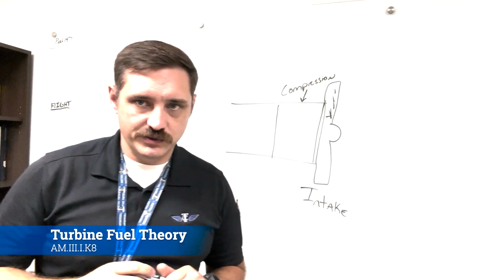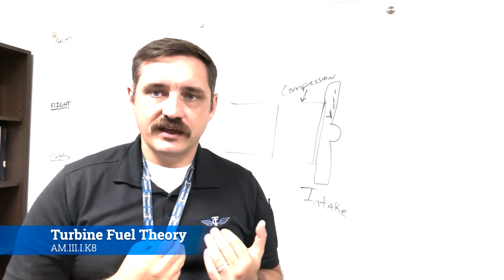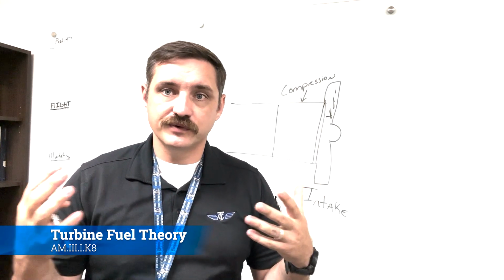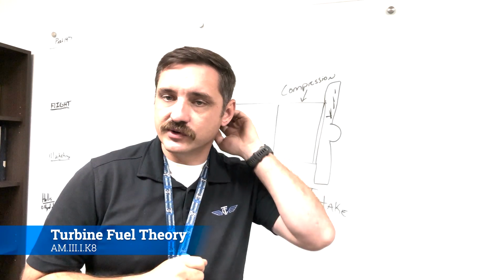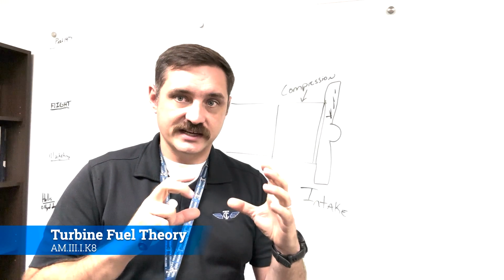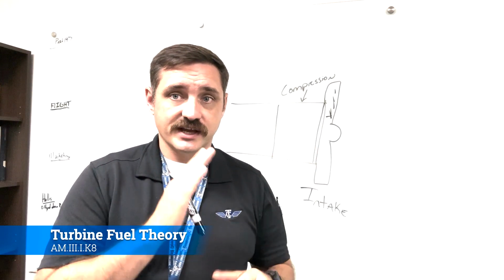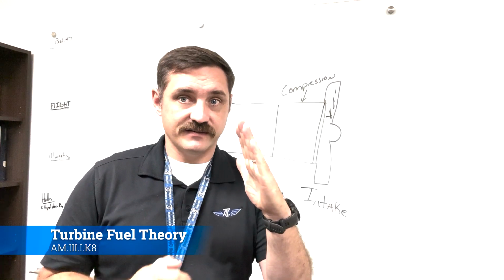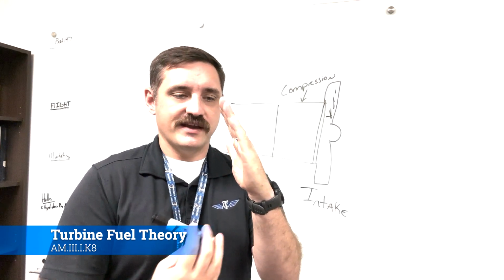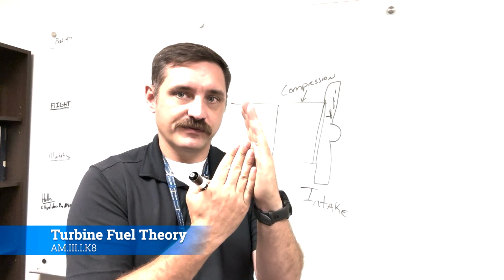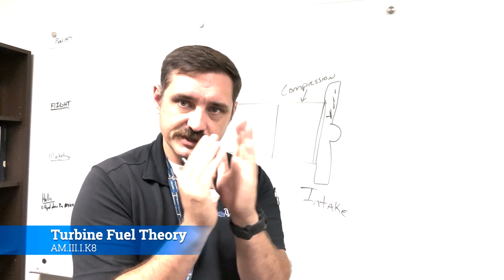Now, how does it do this? It's just like a pump, like if you go back and watch the last video, we're talking about moving fuel around. The compression stage takes a combination of vanes and stators. The stators stay put, and a vane will pass by it, and it has a negative space which pushes the air forward but into a smaller space, which helps compress it.